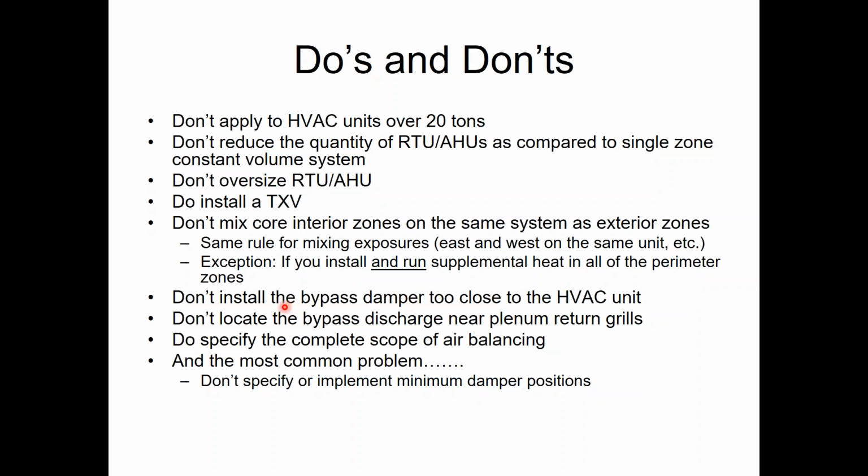If you zone these things correctly, they work very, very well. But if you do it wrong, you'll be that guy that says, oh, I hate VVT, it sucks. Well, it doesn't suck. You didn't use it the way the manual said. Not you personally, somebody else. Don't put the bypass damper too close to the air handler. Don't put the bypass discharge near the return grills or you get that dumping effect.